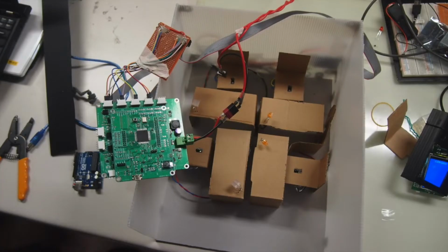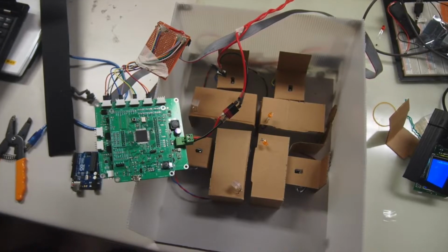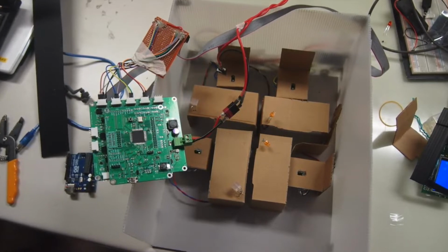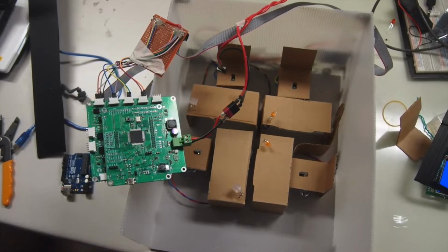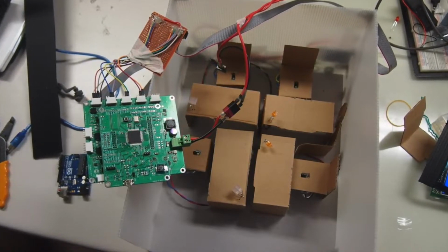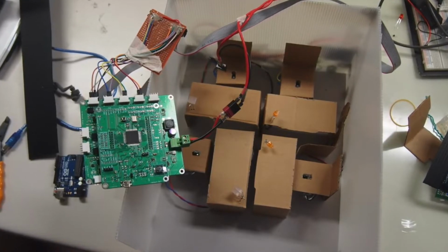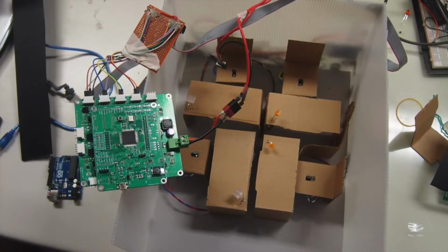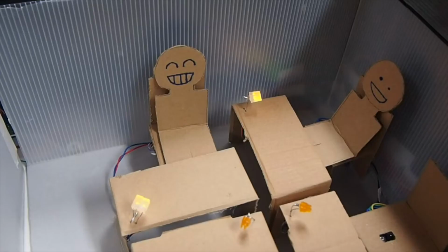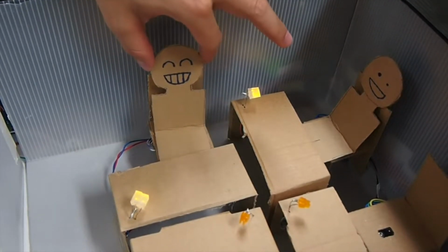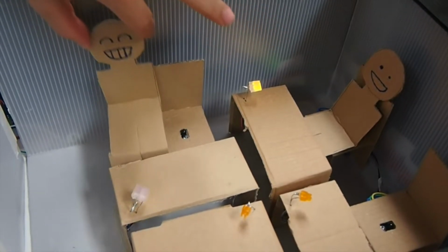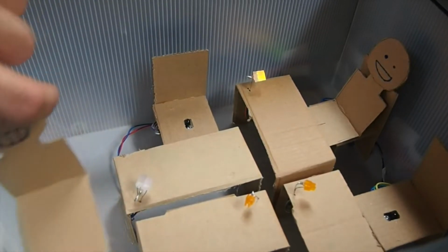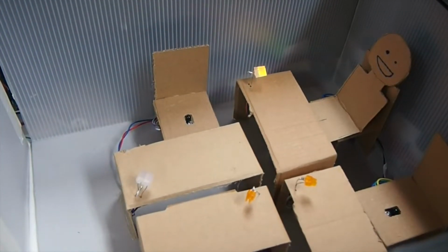As our auto lighting module outputs 5 volts for the PCB, a maximum of 12 auto lighting modules could be connected to the system. This modular design enables a varying number of auto lighting modules to be installed for offices with different sizes. An auto lighting module contains an infrared light transmitter, an infrared light receiver and an LED. The infrared transmitter and receiver are used to detect if anyone is sitting on the seat or not.